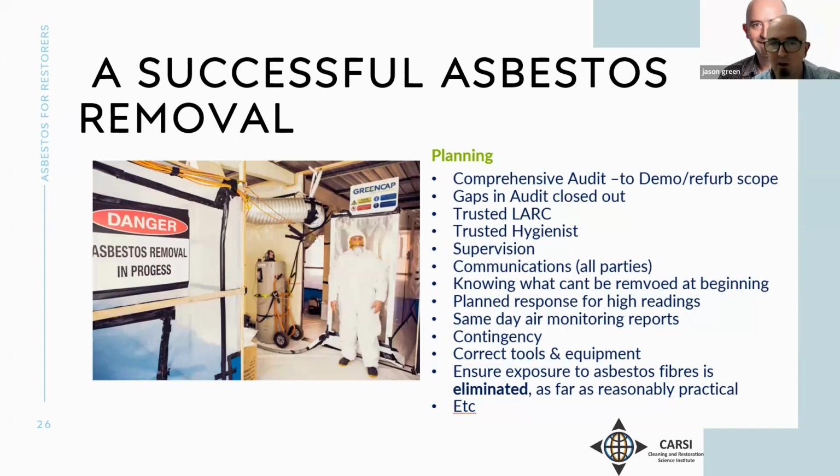So we really need that comprehensive audit. We need a demo audit or survey of the buildings, so that we know exactly where the materials are, what condition they're in, and the extents. Okay, so we want to make sure that those gaps are really covered off, so that we're aware of what's in there. And if there are unknowns, then really strict caution needs to be taken when people are accessing areas that haven't been accessed previously, within areas where you're removing ceilings or walls and things like that.